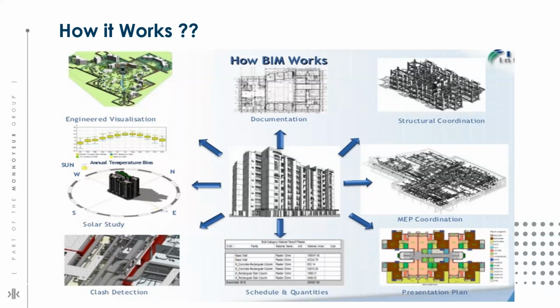Thirdly is a part where it comes with different collaboration and coordination parts. If a number of models are collaborated together, it's quite general that it would have certain deficiencies in them, or I would say clashes in them. So we do have an integrated solution for that. A Revit model can be converted into an NWC file, which is a Navisworks file.